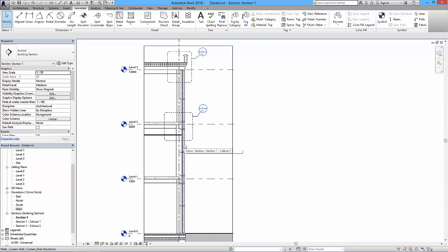It would be far too costly as far as time and modeling capacity went to create 3D everything and hope that we could see everything, because Revit has a way of displaying certain objects at certain line thicknesses when they're cut, but not every object. So certain things like furniture, for example, that doesn't have cut styles because it's just too complicated to start showing all of that information.